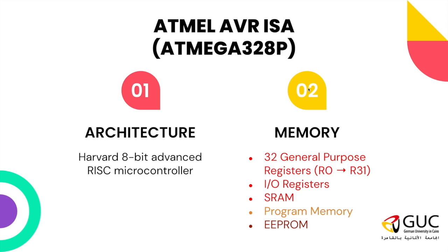And as you can see, a microprocessor will have more computing power compared to a microcontroller because the microprocessor chip is full of CPUs and ALUs, for example, while the microcontroller chip contains other elements. Therefore, the size and the number of CPUs will be less. And definitely in an embedded system, we need less computation power, so we use microcontrollers. We do not use microprocessors. Also, because of the space, we cannot externally connect other elements like the memories. So everything is on a chip, and it is called a microcontroller.